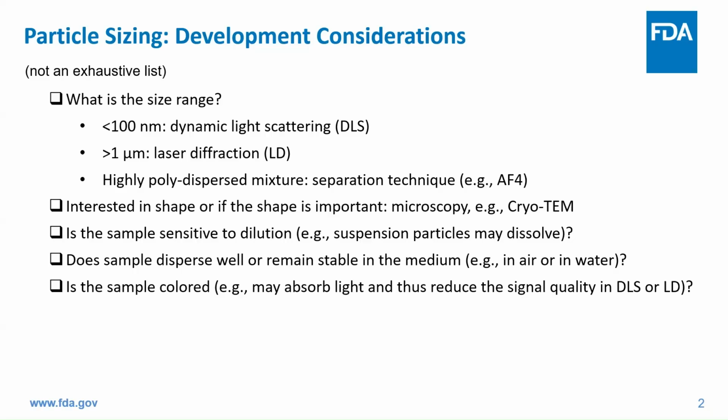Now, we analyze the size, we analyze the particles, by measuring what's being scattered. And because the sample absorbs so much light, it really doesn't allow you to actually see the scattering signal from the particles. So if the sample is highly dark colored, you should recognize this is inherently a challenge to measure.